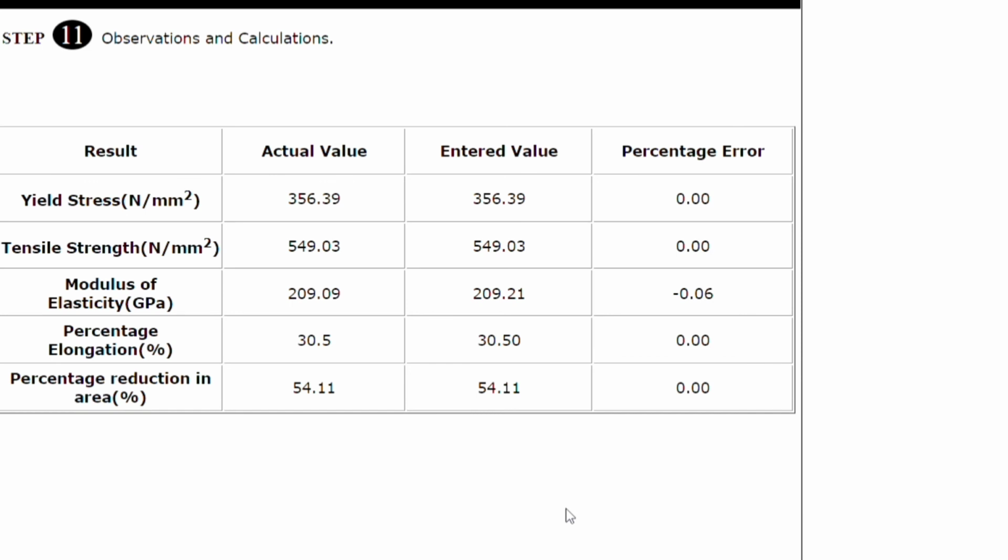The conclusion is that the carbon fiber composite material has a much higher tensile strength and modulus of elasticity than the other materials. Note they all break in a brittle manner, as the curve is linear until it breaks or fractures with no bending of the curve at high loads. Consequently, there is no permanent change in original shape during this test and hence no ductility. And that's all for this test.